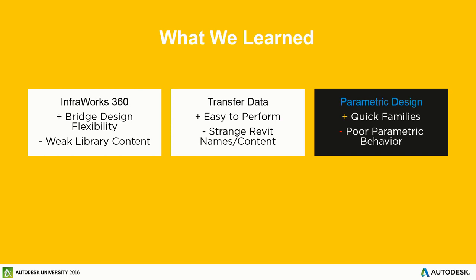From the parametric Revit designing aspect of it, the families are generated very, very quickly from InfraWorks. It's really good. I can very quickly generate the bridge, get an overall sense of the placement and the shapes and everything, bring it straight into Revit, and I have a design. I can work with this with what I have.